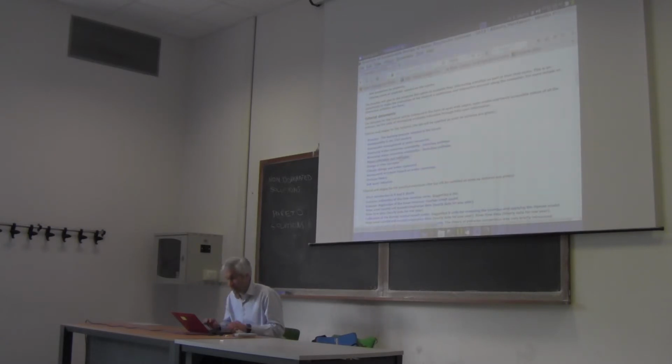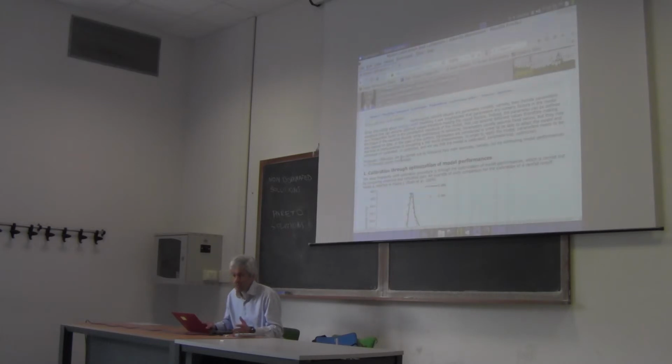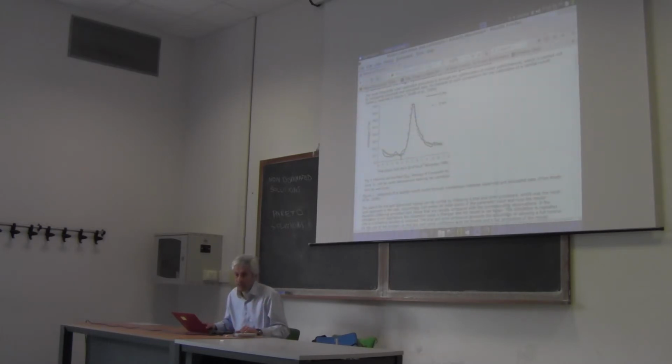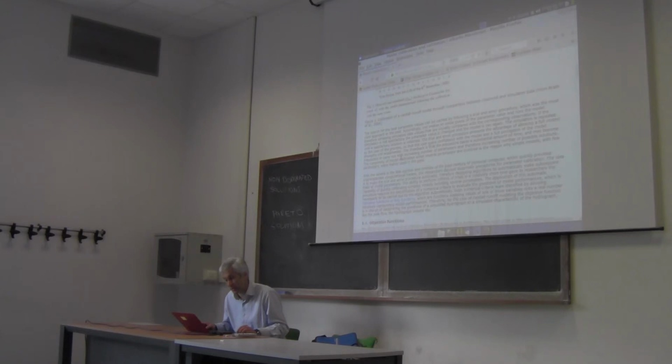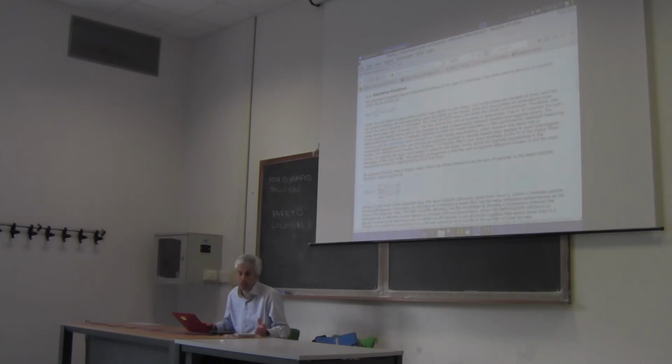Model calibration and validation. Typical question is objective function. Please write down what are the objective function that we considered. And another typical question is calibration procedures. Just speak about it. Trial and error, manual calibration, automatic calibration, advantages, disadvantages, etc.